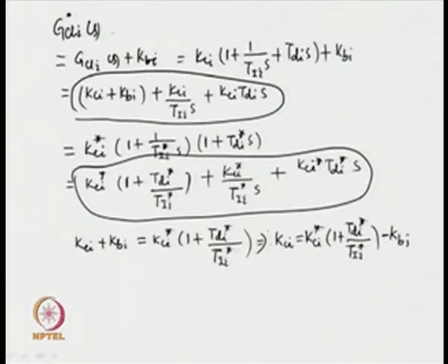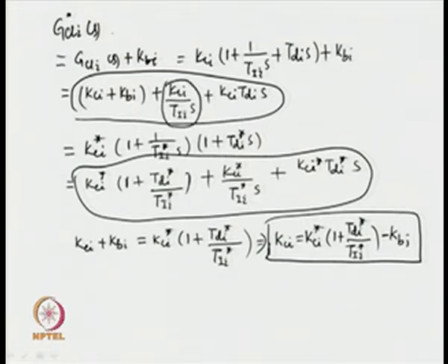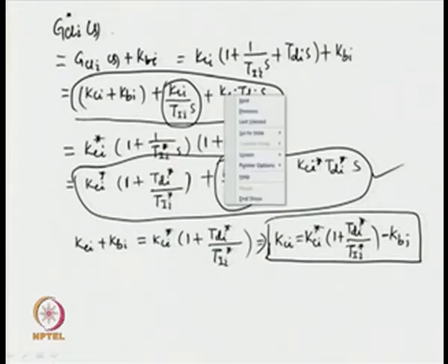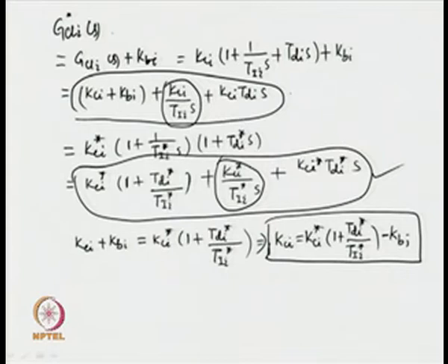That is how we obtain the same relation. So, using other terms upon comparison, we have to see that this term must be equal to this term, because we are comparing the dynamics of the transfer function form of the new controller with that of the parallel PID controller and the additional proportional controller in the inner feedback path. So, obviously, comparison of this term with this term gives us